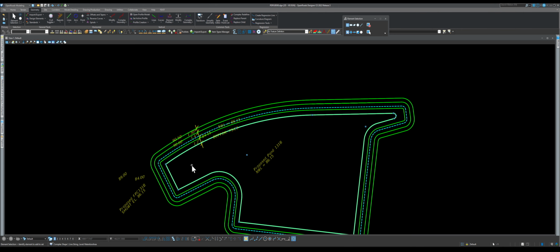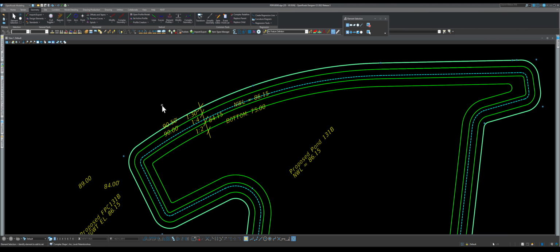One of the most important things is, if you have a change, for example, this diameter, I mean, what is this? The radius, I'm sorry. The radius of this is 45. If you want to change it, what you need to do is drop all of them, then change this one, and after that, go again and make the other ones. It's extra work. But if you use the smart lines, there are ways of just changing it, making, for example, this one to be the father or the mother, and then all these will be children under it. So if you change this, it will change the other ones.